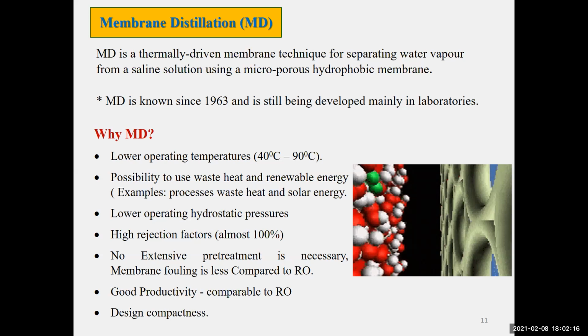Whatever the quality of water that comes in, the results are very pure. It is evaporation. In RO systems, the product has a certain salinity, in the order of a few hundreds. But here it's basically zero, because it's evaporated and condensed vapor.